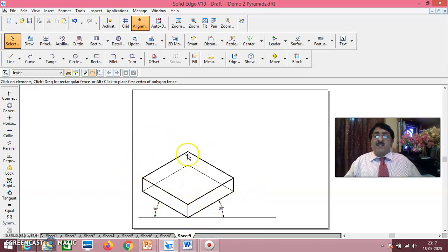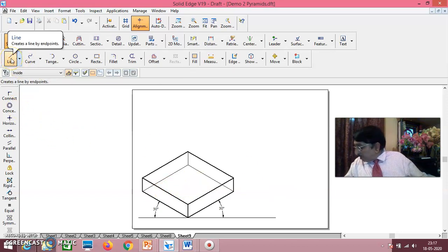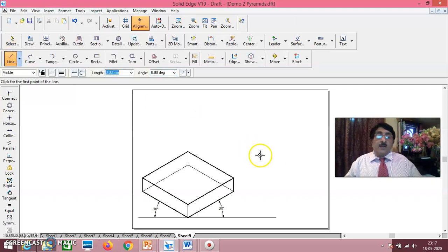Since here sphere and hemisphere are not there, you can do isometric view completely, because you don't have to multiply again and again and all that. That is why directly do actual dimensions. Finally, you take the scale, multiply by 0.816 and convert into isometric projection. Anyway, I'll show. This is the isometric view of the bottom solid. Then you see here, top solid you draw. Top solid is a frustum of a square pyramid. Okay, frustum of a square pyramid.